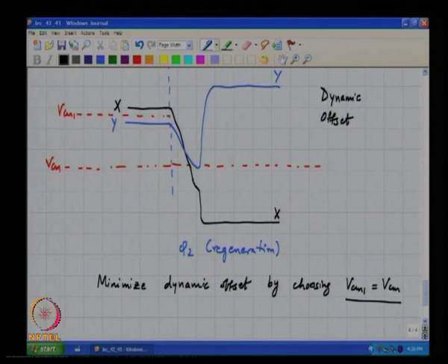All these problems will only happen when the input is very small, and therefore, you need to run a whole bunch of simulations where you randomly vary the thresholds as well as the parasitic sizes to get a good estimate of what this random mismatch, the dynamic offset due to random mismatch, which will include both effects of nonlinearity of the capacitances as well as mismatch between them, are taken into account.